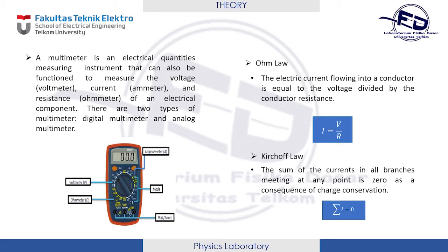What is the difference between series and parallel circuits? Components connected in parallel are connected along multiple paths so that the current can split out. The same voltage is applied to each of them. But in a series circuit, the voltage can split up. The same current is applied to each component. So you just need to remember that. Okay?